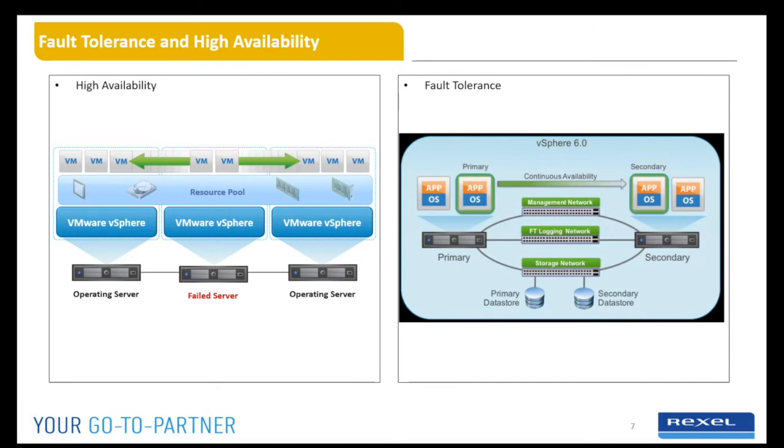How you decide between highly available or fault tolerance is based on criticality. So like we talked about earlier, if you have a historian and you're in a heavily regulated industry where fines can be assessed based on lack of data, typically somewhere like that you would use fault tolerance. That way your data is always backed up, is always being captured when it's being created. Something else though that's a little less critical, like a domain controller that can handle being down for 10 or so minutes while the system reboots, something like that can be done in a high availability state because you're not necessarily relying on the continuous uptime of a system like a domain controller.